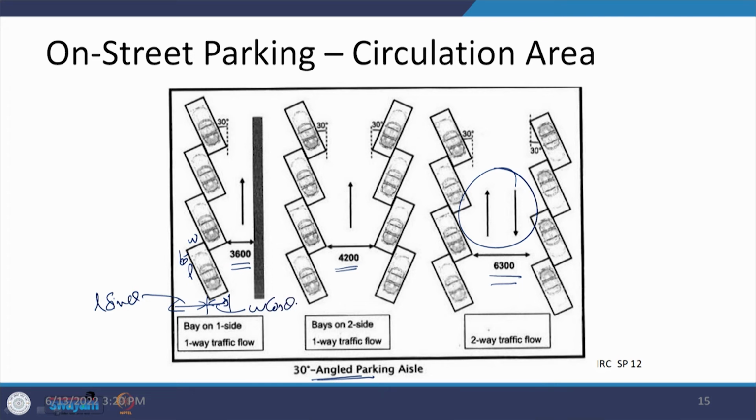So, this is the amount of space which is going to be utilized by this parked vehicle. Along with that, if we are looking at this space, then this is going to be L cos theta and this will be W sin theta. Together, these define how much space along the length of the curb is being utilized. This is the same thing which can be done in the rest of the cases too.